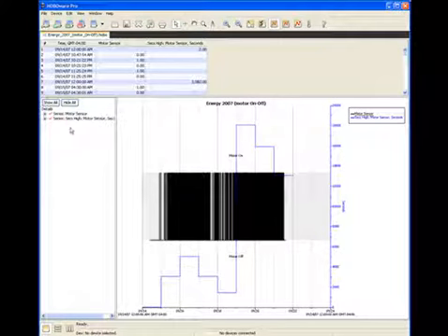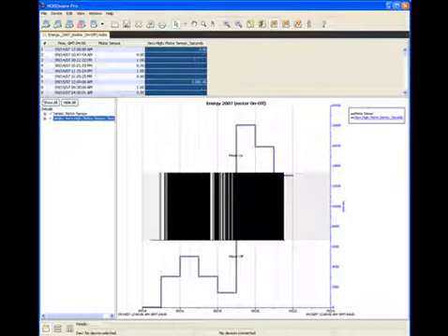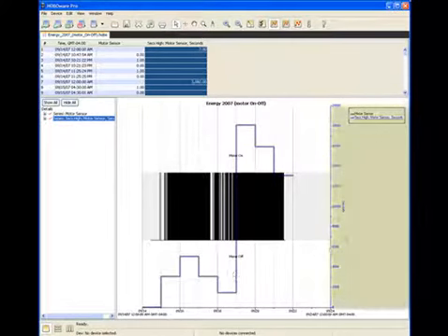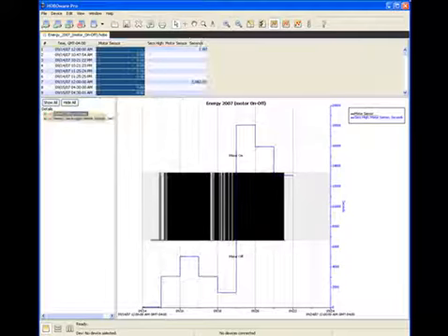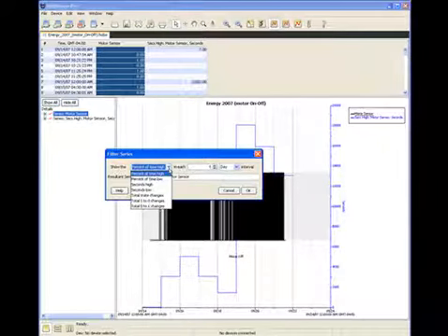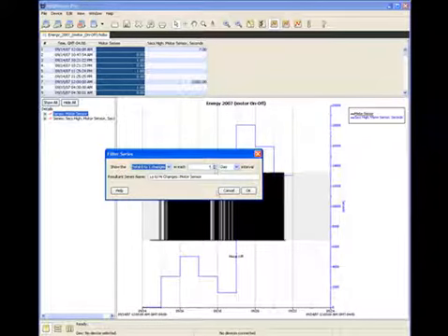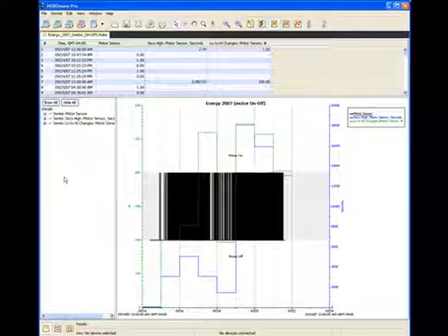For the purpose of this exercise, we can highlight the new data, and basically what you get is the total number of seconds per day that the unit was running. If you divide that by 3,600, you'll get hourly runtimes per day. The other thing people like to use is, we're going to filter it yet again, the original plot. We can see how many times the machine turned on per day. So this is 0 to 1 changes. If we click on this, that gives us the total number of run cycles per day.